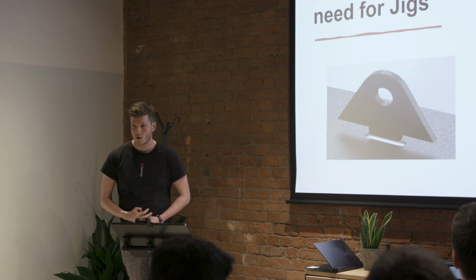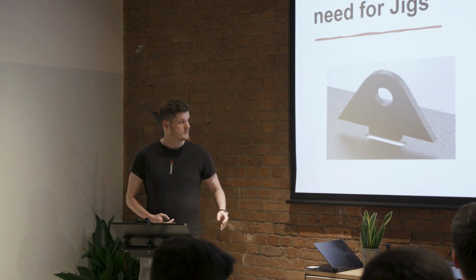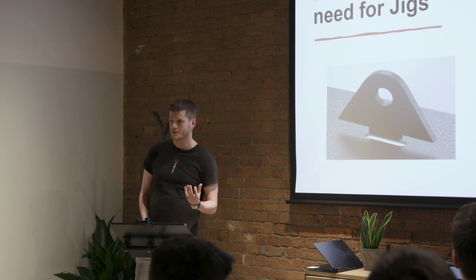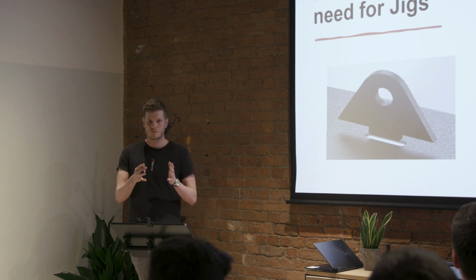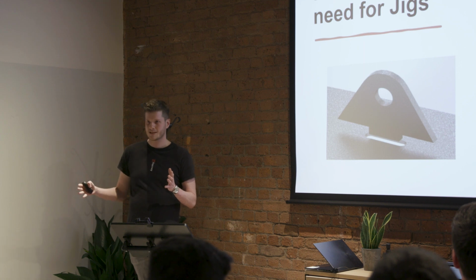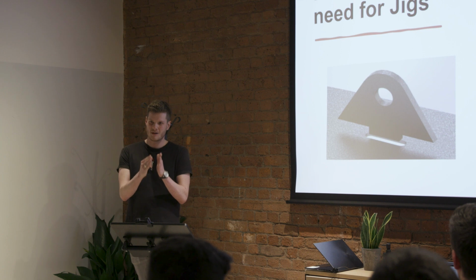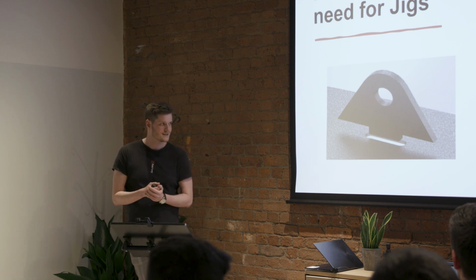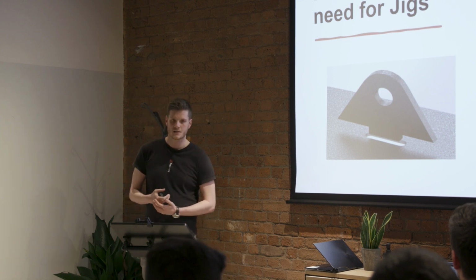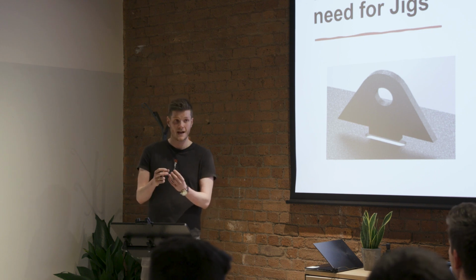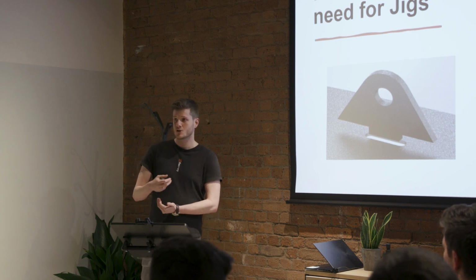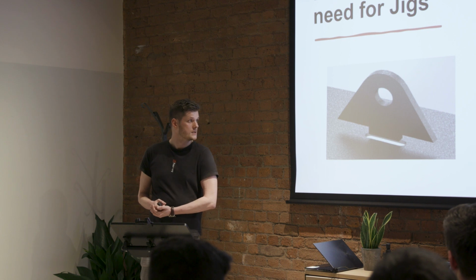One thing to note here, if you are going to design, however, is to make sure that the slot is slightly oversized, just because of the tolerances on, say, if you're having these laser cut, it could be on the minus side, meaning that it might be a bit undersized and not quite fit, which could be a bit of a nightmare. So speak with your production team at what size that needs to be, just to make sure that it will work for you. But you will save substantial amounts of time.